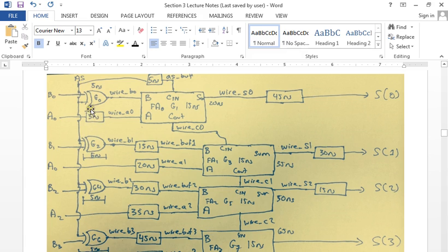And then I delay this by 5 nanoseconds, and this becomes 15 nanoseconds. So now this output comes out at 20 nanoseconds like I have here. So this is also going to come out at 20 nanoseconds, which means I want these to come out at 20 nanoseconds, right? Buffers of, so this is 5 plus 15, because your XOR is always going to be 5 nanoseconds.